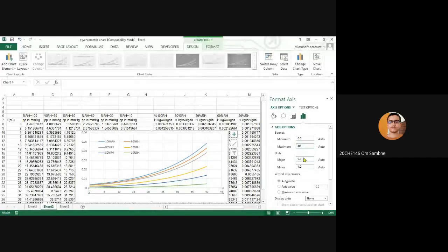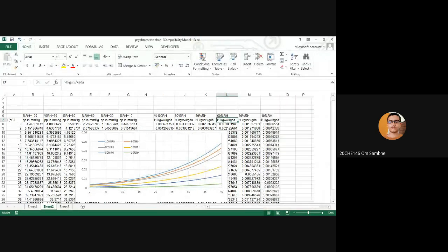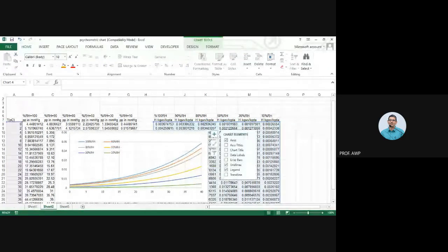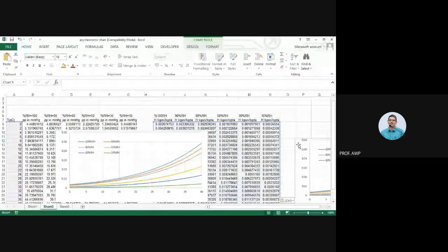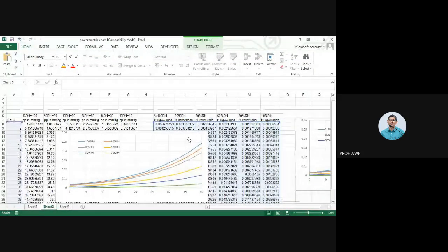Sir, can you show how you changed it once? How did I change what? The graph, the same graph you changed. Yeah, so just copy this graph somewhere else. What I did was just select the graph. It is highlighting, no? This blue first column, the A column, is highlighted. That is our x-axis. Do you see them in a blue rectangle? Yes, sir. So you just hit anywhere on that blue rectangle and drag it to wherever you want it to plot.